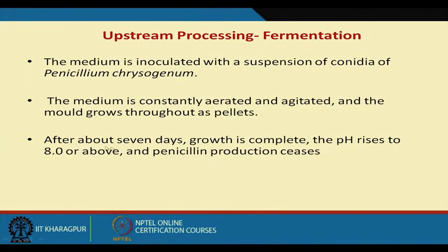The main purpose of the agitator is to keep the cells in suspension, but unless they grow properly, we cannot put it on. When they grow properly, then and only then we put the agitator on. So there are different ideal times for the production fermenter and for the inoculum vessel, which vary from fermentation to fermentation process.